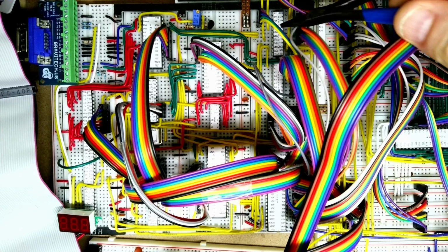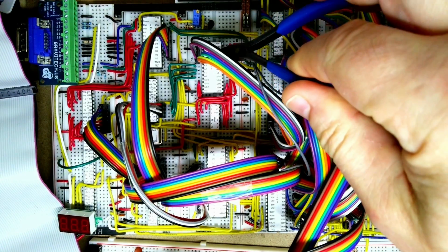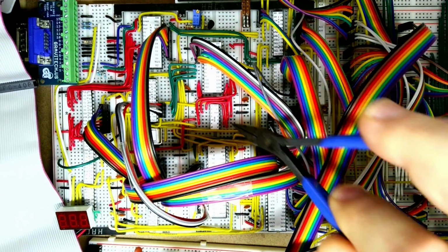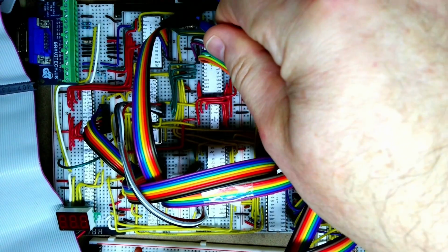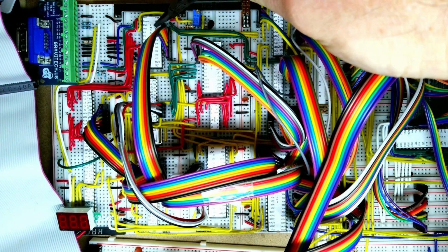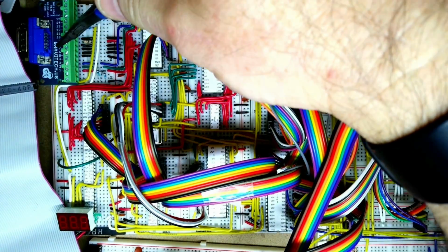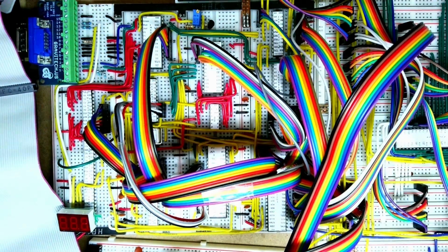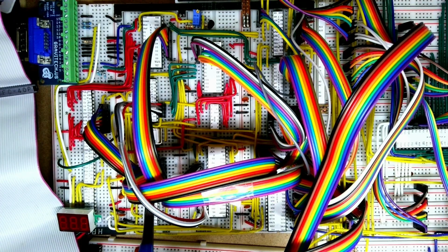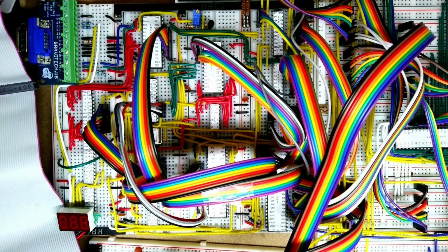Then we've got various things like address decoders, I think there's a character latch there, and this is our character ROM here. This is the shift register. Over here we have the VGA output, the digital analog converter with our 15-pin subminiature D VGA connector. Then there's some more logic around here, the attribute latch and various other supporting chips to handle all of the attribute timing and multiplexing.